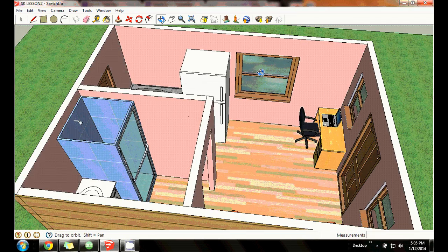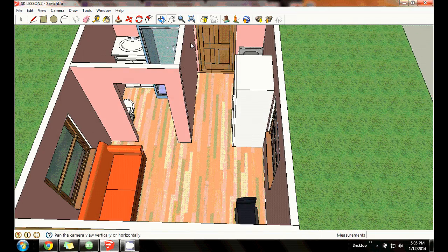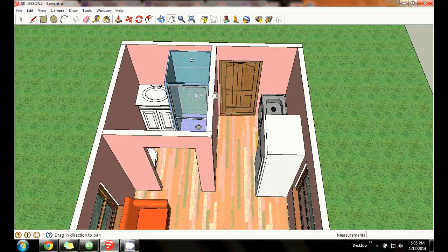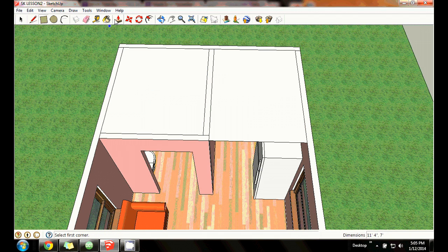And now what we want to do is a bedroom, and we're going to do a loft bedroom in these houses. That's very typical for these. And doing a loft bedroom platform is really pretty easy to do. First, grab your rectangle tool, go on the inside of that corner there, because you have to remember that your platform is going to sit inside of the roof wall. Let's do this again. Let's grab our rectangle. We'll go to the inside of this corner over here and over to the front edge of this corner over here. Create our platform.